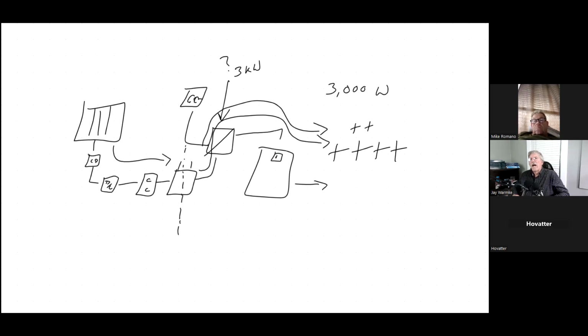If I undersize it, it's going to squeal at me and it's going to turn off. It's like breaking a circuit breaker. You've put too much juice through it and you've basically popped a circuit. If I have an array or an inverter that's undersized, you can burn them up that way, that's for sure, especially cheaper ones. For the most part, more expensive ones have circuit breakers or fuses inside.